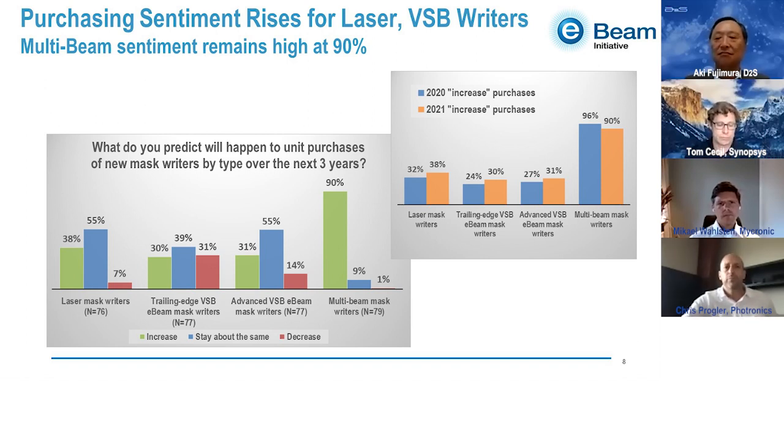I think there would be more use of that technology if we could solve that. And the so-called repair-what-prints, you folks probably all remember it. This used to be a big effort many years ago in the mask industry, where you have enough inspection capability and know-how that you only worry about repairing things that print or that are going to have a direct impact on the wafer.